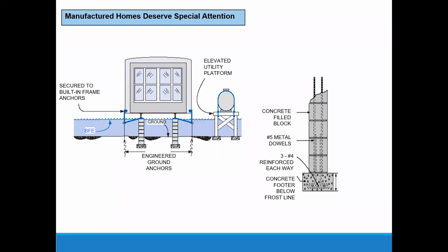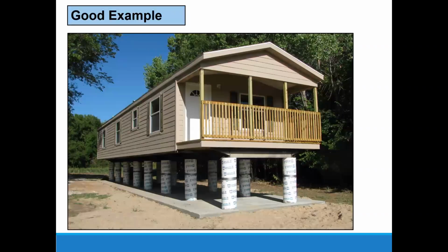We often see piers, posts, or columns as the type of foundation for the manufactured homes. As I said, cement bricks like this that are at least reinforced and anchored is the proper way of doing it. And so we do have the protecting your manufactured home from flood damage publication from FEMA, and there's a few other publications on that. And so it does come up pretty often.